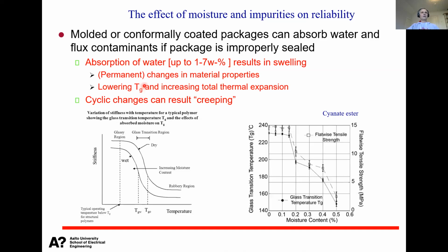And also this moisture going in and going out causes a similar type of changes as thermal cycling or creeping, so that the polymer chains are not recovering back. So you basically end up increasing the volume of the organic material, even when the moisture is not there anymore.